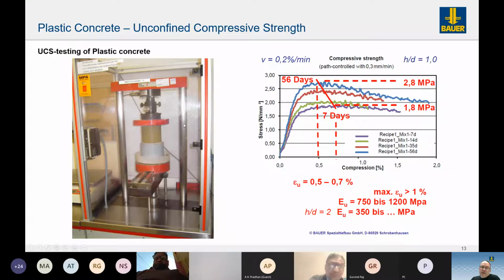For concrete, for dams, we typically use so-called plastic concrete. Most of you are aware of plastic concrete. Plastic concrete is a more ductile concrete. It's a concrete where we typically add bentonite, and this bentonite gives a certain ductility. The strength is much lower than a structural concrete.